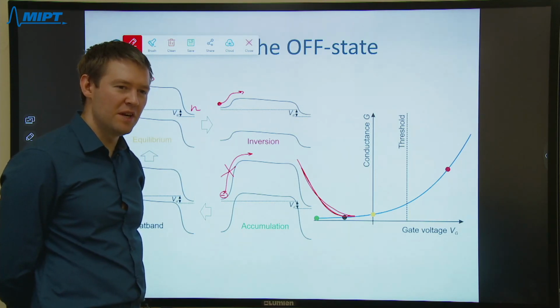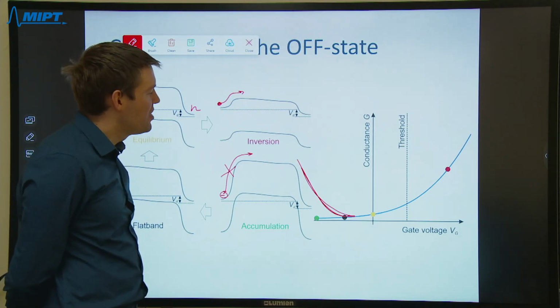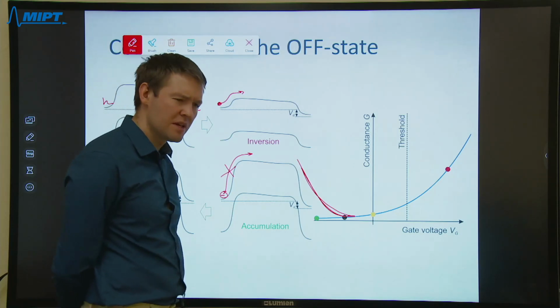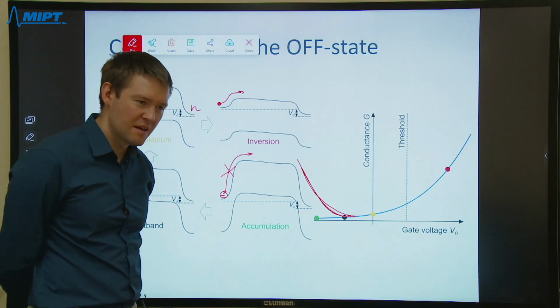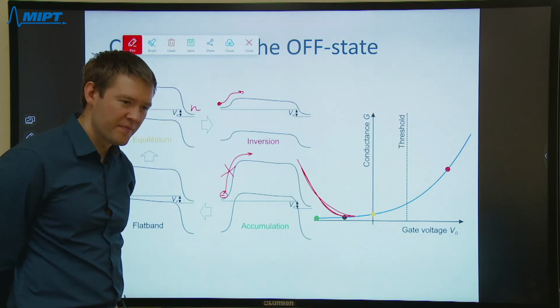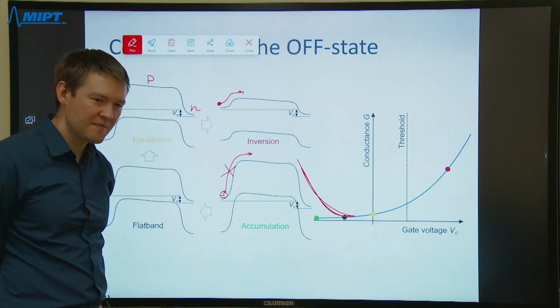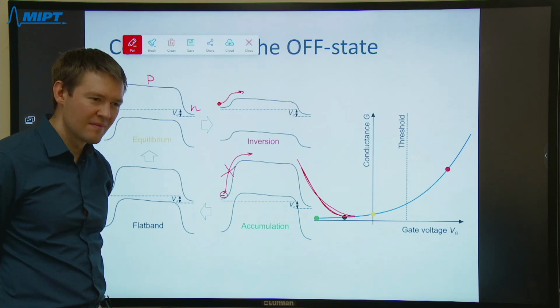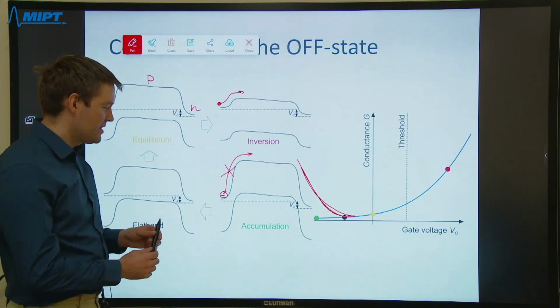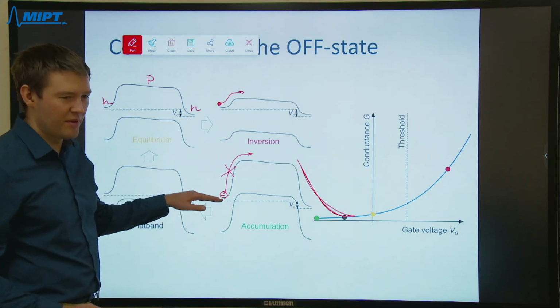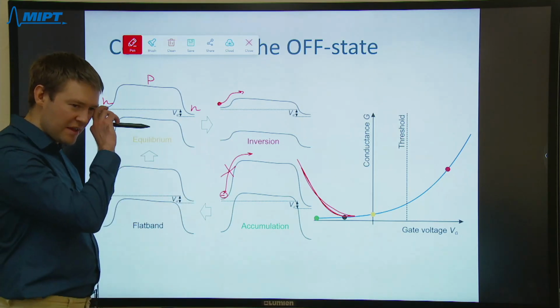It's a good observation, but how is the band gap related to the conductance? So when we have a negative gate voltage, we don't have to tunnel, so the conductance increases again. Yes, it's a great answer, and it is very clear from the band diagram